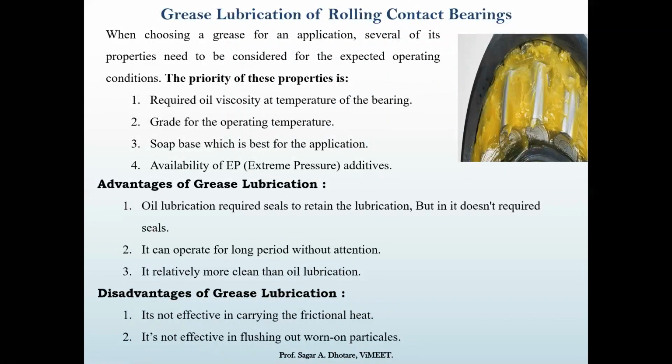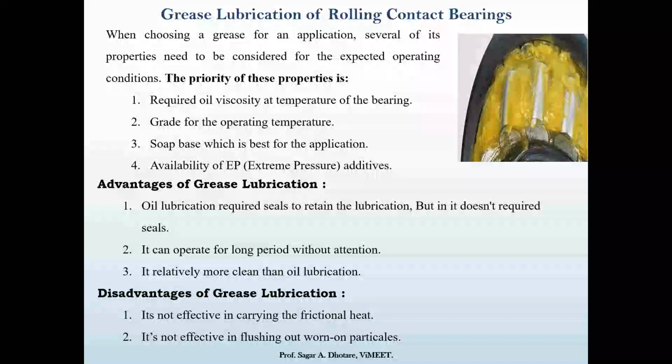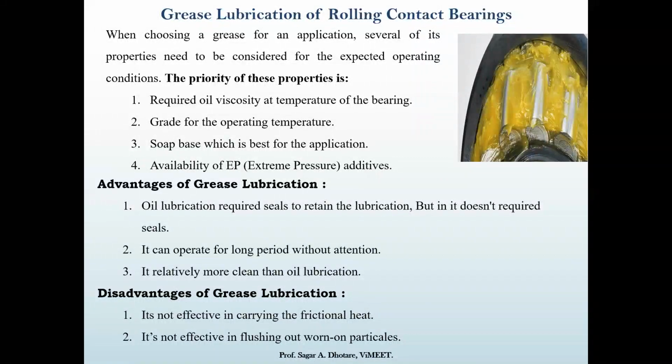It's not effective in flushing out the worn particles. Yes, it's the biggest disadvantage of grease, because grease will not move from its position. So whatever worn particles or dirt may be trapped between the bearings and balls cannot be flushed out. It is always kept with them.